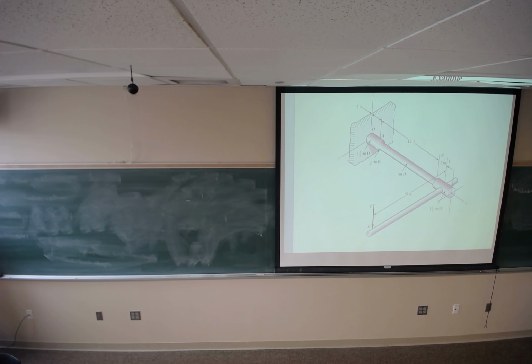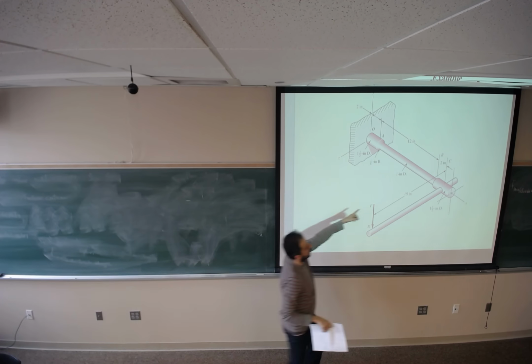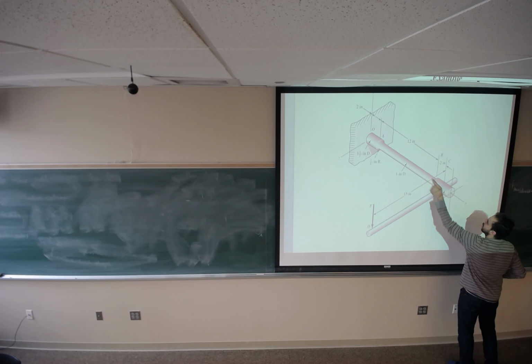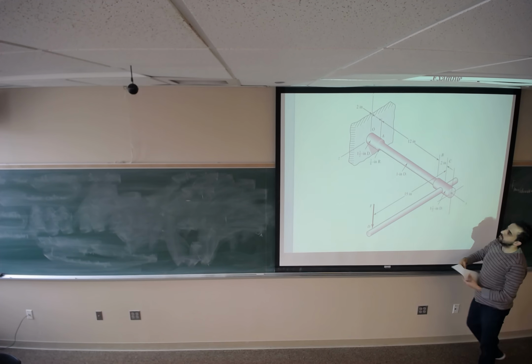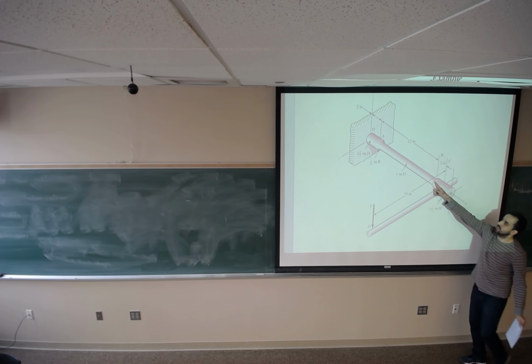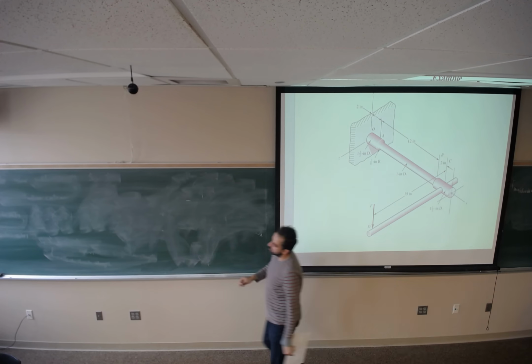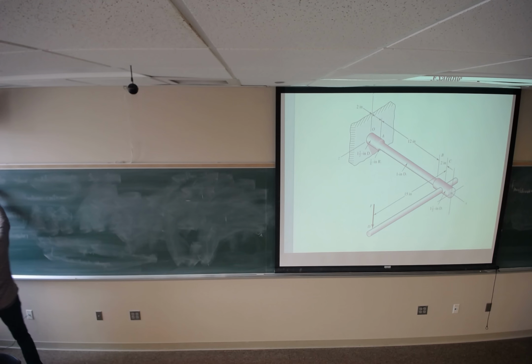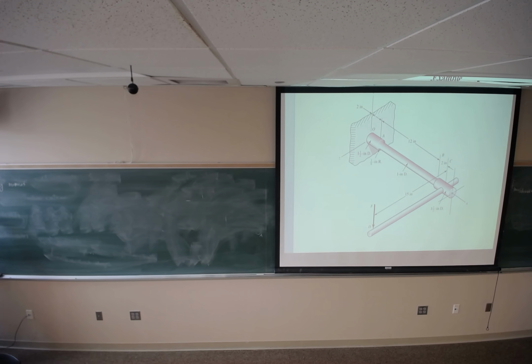MZ, the axis of this component is x-axis. MZ has a different direction than the axis of this component, so it's going to be the bending moment. So 14F is going to be bending moment. This MX is going to be the same as the axis of the component. It's going to be the torsion or torque.